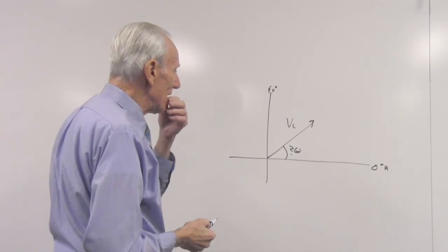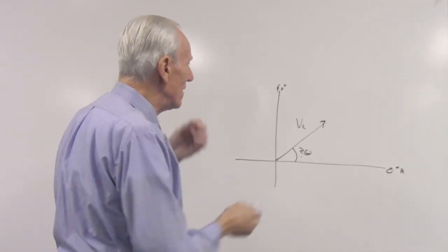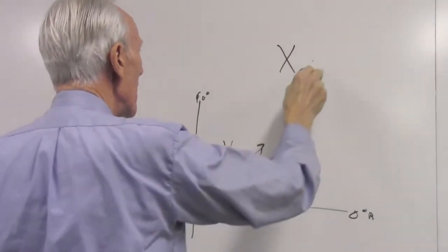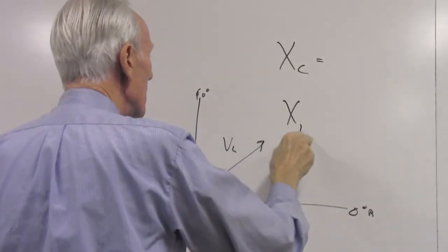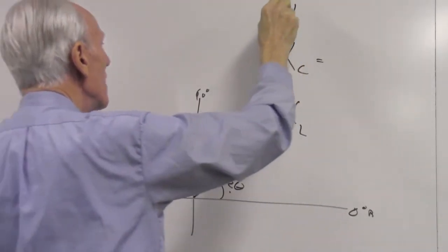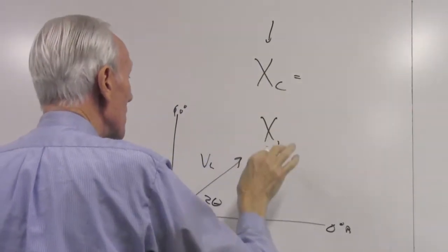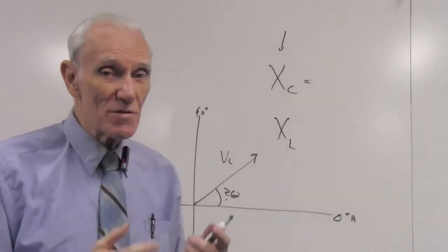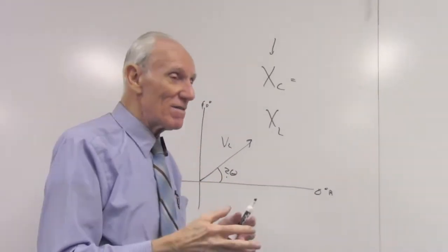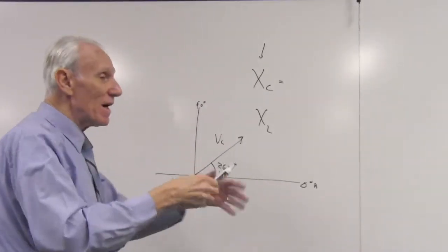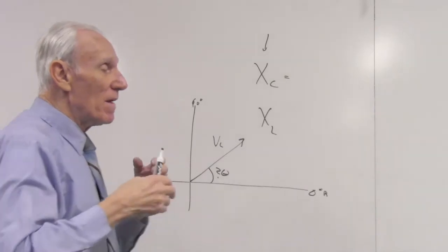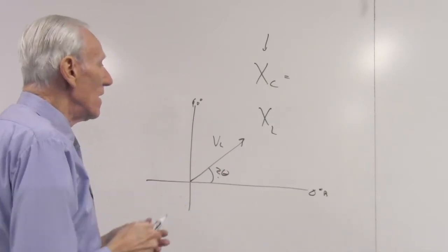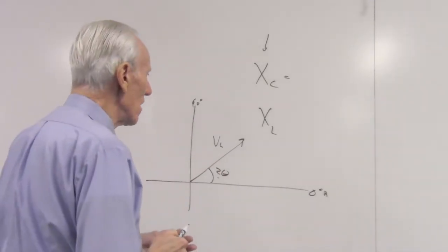And in fact, that's not too far away from the angle you're going to get for this inductor. The inductance depends on, well, here are a couple of formulas we need to talk about. These are called inductive reactances and capacitive reactances. These inductors and capacitors are active circuit elements because they shift things around. They actively take some time to charge up for a capacitor, and they actively resist a change in the magnetic flux through the inductor. And there's a minus sign involved there, which is called Lenz's law.